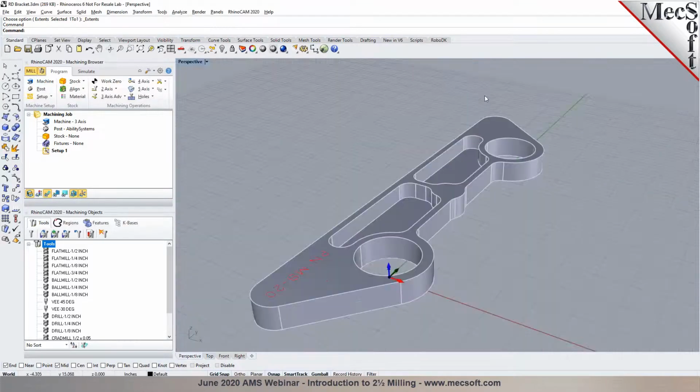What does that terminology mean, and how is it different from other machining methods like 3-axis? 2-axis or 2.5-axis is typically used for machining or programming of prismatic parts, where there are no negative drafts or draft tapers, and it's like a straight extrusion with either a planar floor or through a hole like what you see here, and there are no sculpted surface geometries in here.